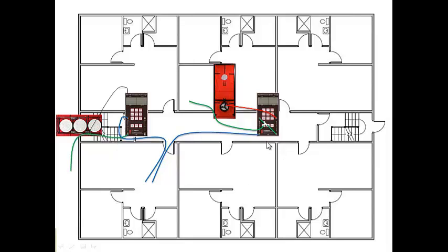So now we've got our tubing connection set up. Another thing that we can do to make sure the building is at 50 when we take our readings is we can add a Wi-Fi link to our DG700 that's cruising our outside pressure, and then with our phone we can use the iTech 700 app to see what the building pressure is and make sure it's at 50 pascals when we take our reading.